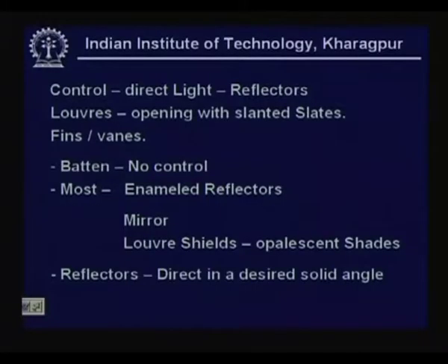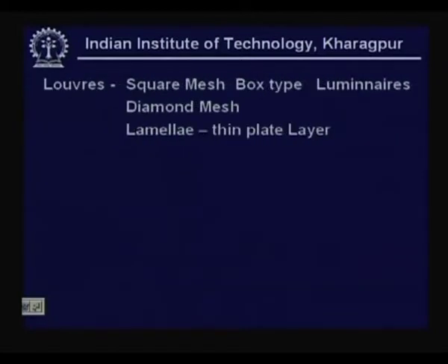On the other hand, with the help of various luminaires along with diffusing shades, it is possible that we get nearly a plane source of radiation or a sheet of light which is independent of the mounting height. That is what we look for, especially in office lighting, and the reflectors enable this. And of course, as I told you, depending on certain applications we can orient it in a desired solid angle.